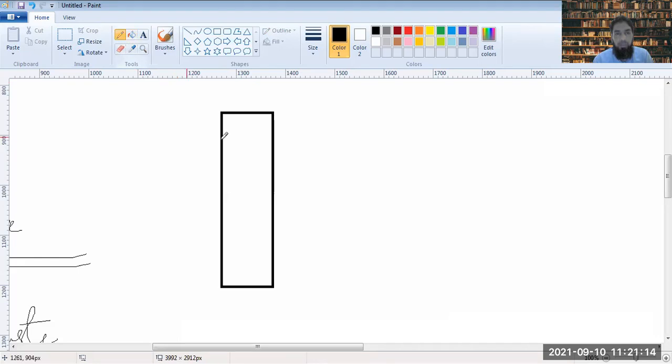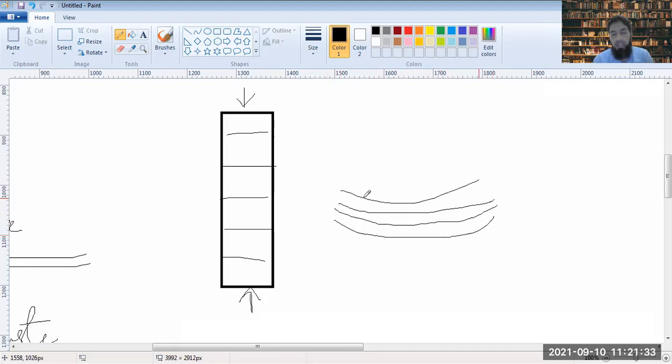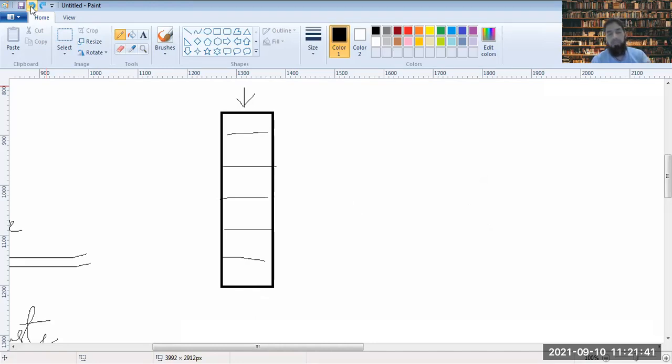So when you're pouring concrete, it settles down in layers, and this is good in this case. Why? Because the load is a compressive load over a column, and the layers ultimately compress out. While in a beam, the layers would behave separately if you are casting in that fashion. In this case, the compression load is there, so it would behave in a better fashion.